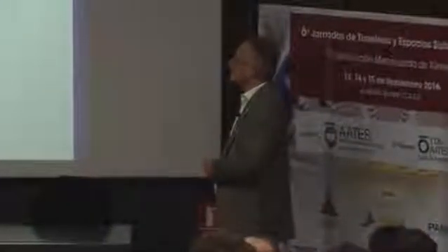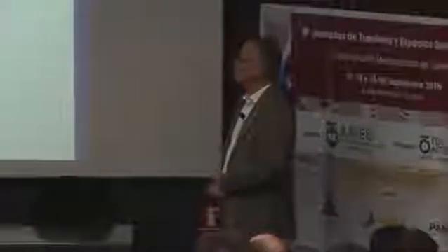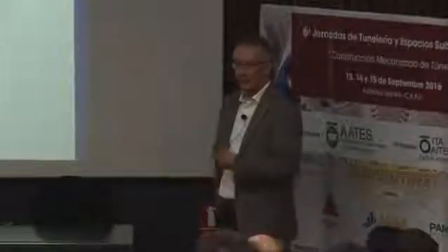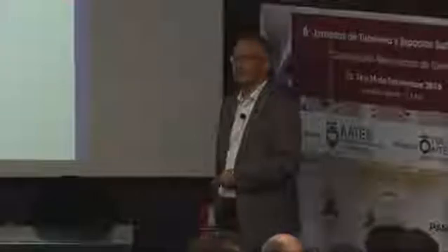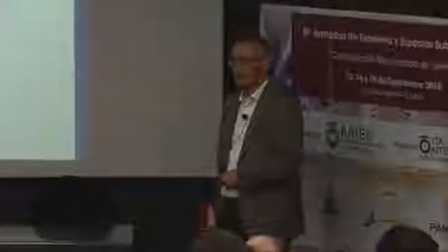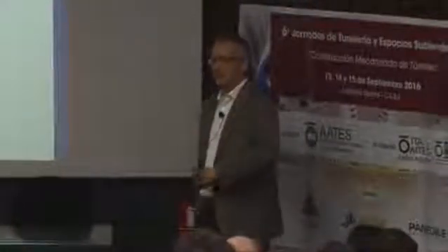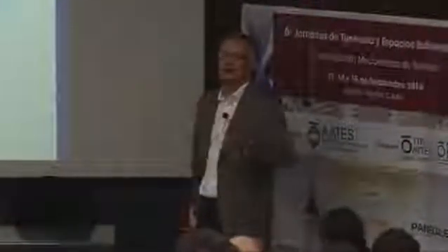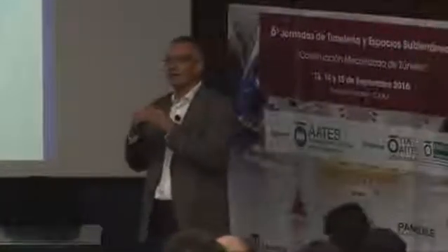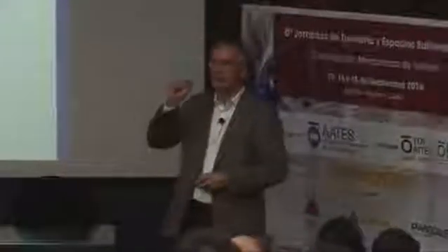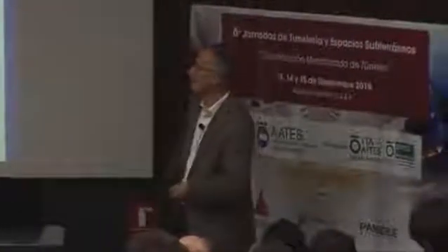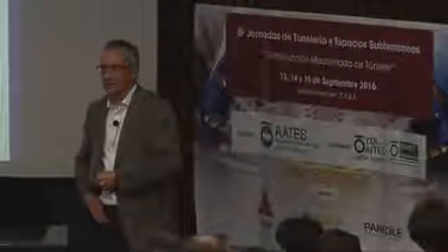So, summary: understanding the face support model used, and having an idea what the limitations are. That is a very important fact when you are starting with a certain face support pressure, which you have received from an engineering company, that you practically know what it is about. Where are the limits? What is my flexibility within there? It's not a fixed value, it has a range. The tolerable face support range should be calculated. As I said, not only the lower limit, the higher limit is as well very important to know.